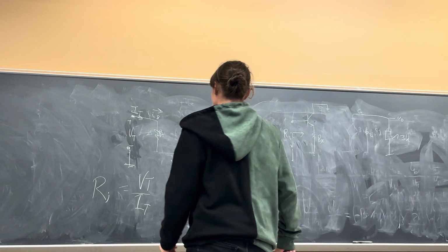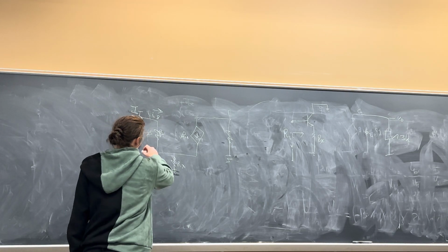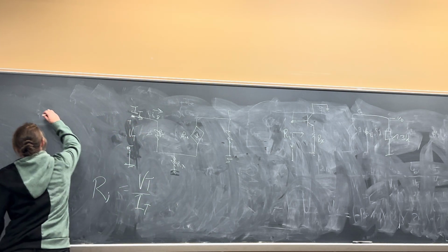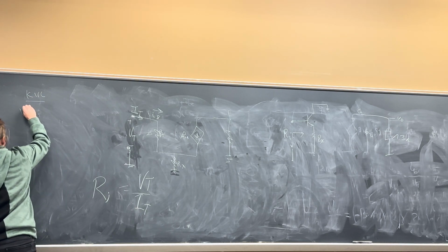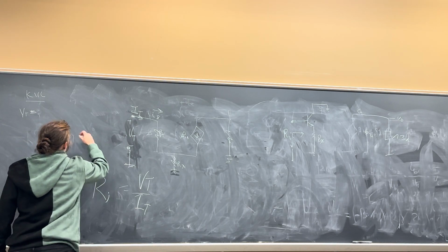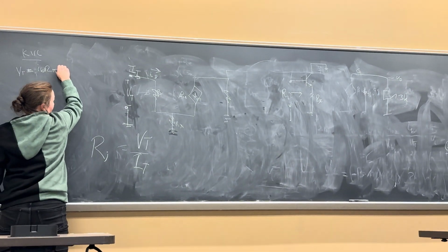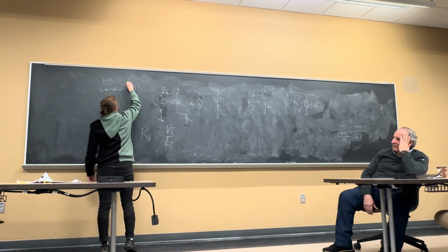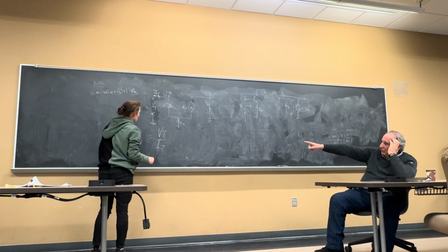I like the VT, confidence. Do KVL. Doing KVL here, VT. All right, so you're better than you think. We're going to have VT equals IB R pi, right? Plus beta plus 1 Rx, right? And the big Rx right there. You understand that KVL?